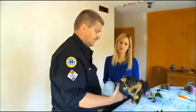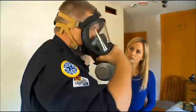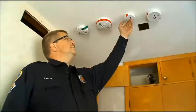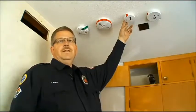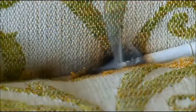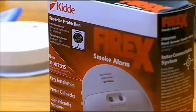So we went to one of the leading experts in Minnesota, Jamie Novak, to put them to the test. There are 3 types you can buy. This is the ionization smoke detector. This is normally the one that most people have in their house because they're the most inexpensive. Ionization tend to detect open flaming fires faster, and photoelectric tend to detect slow smoldering fires faster. There's also a dual sensor, which incorporates both technologies.